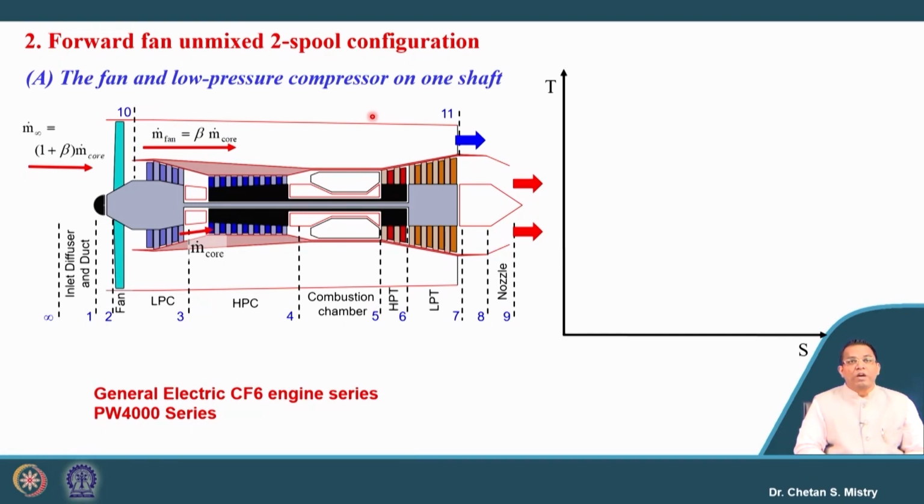So, what all we have discussed for turbojet engine in terms of single spool configuration and two spool configuration, the logic is similar here. So, over the year, as we have discussed, there is a requirement for higher and higher thrust. Later on, people they have realized in terms of lower specific fuel consumption, people they started talking about the fuel economy, and that is what has given some innovative ideas in terms of configuring the turbofan engine.